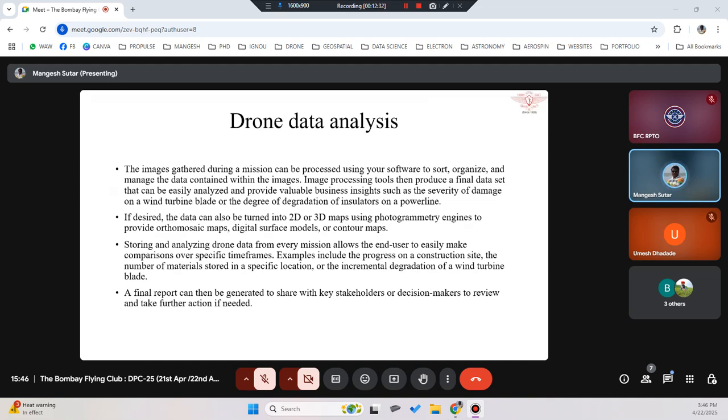Okay, so I checked with DJI and other teams, and they suggested that you have to fly a drone a little bit away from the power line towers, maybe something around 5 to 10 meters away from the tower, and then capture the image. I should not go beyond 5 meters of the tower, just to safeguard my drones.